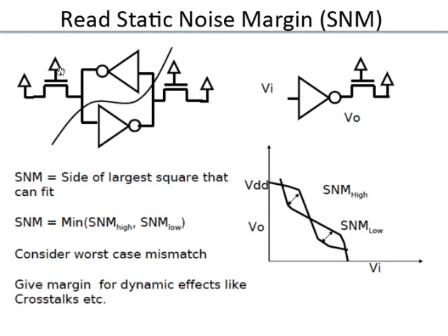So I have just indicated them here by the gate connected to the high supply. Similarly, the bit lines are also pre-charged high. So as soon as you turn it on, both the bit lines are at VDD, both the gates are at VDD. Now what you do is you take this and you cut the cell like this. You make a half cell. So a half cell consists of an inverter with this access device connected in the output connected to VDD.